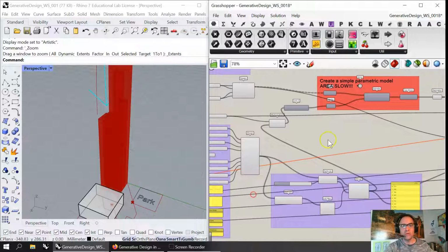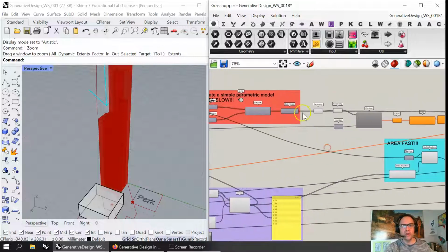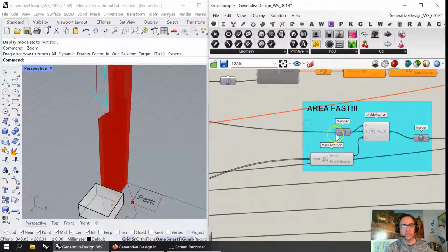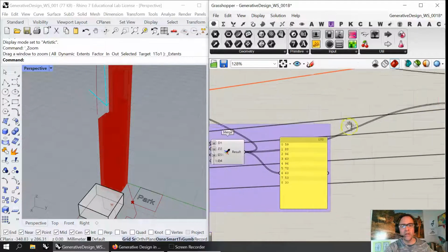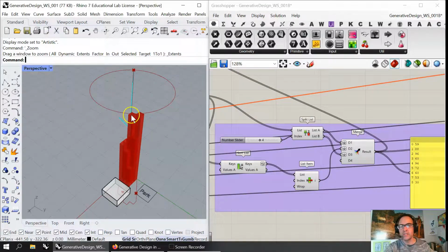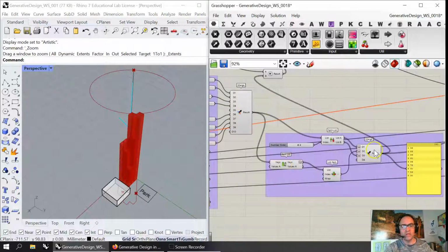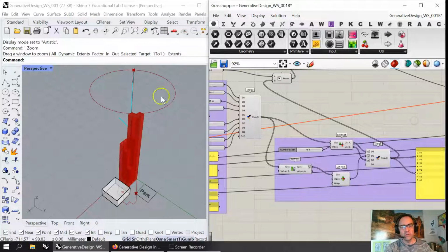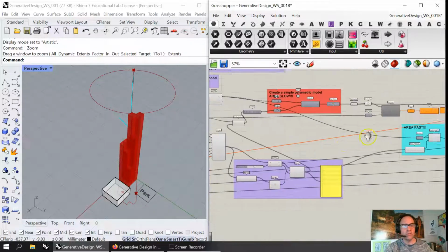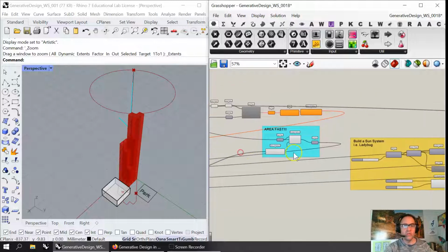What I hope to do is create, and you'll see me run through it, the slow method of using contours and how to get an area, whereas he does a much faster form later on. There's a little bit of merging because this model is specific to keeping the center column at least as high as the highest model. So he has to do a little bit of resorting here, so you'll learn something with the sort keys, which is always nice in remerging data, so you don't have a loop happening within Grasshopper, which is not possible. I'm not using ghpython or C# nodes or any custom nodes in this.